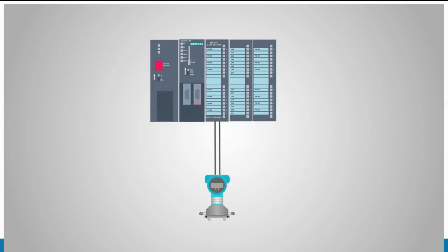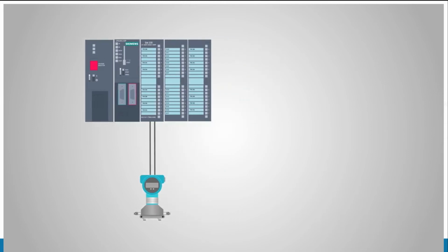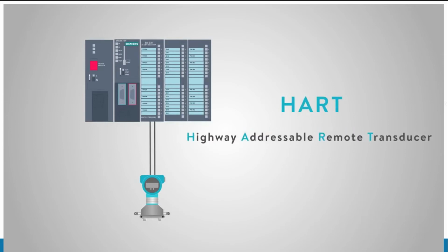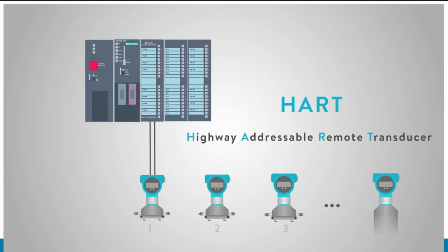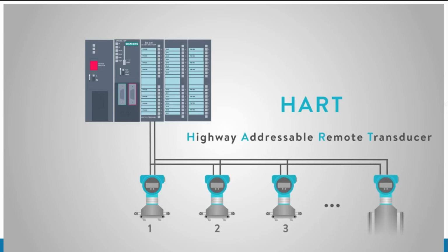Now that we know what HART is, let's finish the discussion of how HART works. First, HART is an acronym for Highway Addressable Remote Transducer. This simply means that a small network can be formed with up to 63 HART devices, each having its own address, or node number. Because a sensor can be remotely accessed using HART, the name really does say it all. Highway, or network, sensor, also called a transducer, that has an address so that it can be accessed remotely and directly.